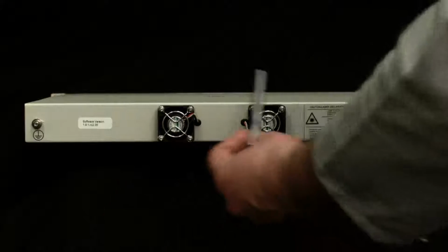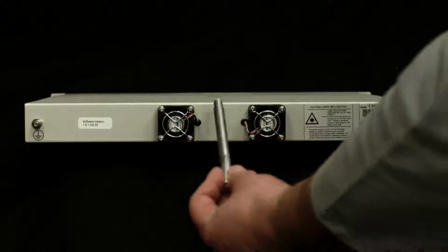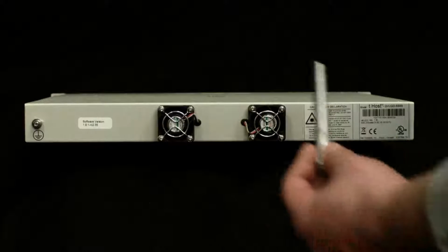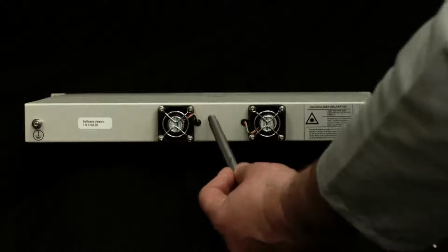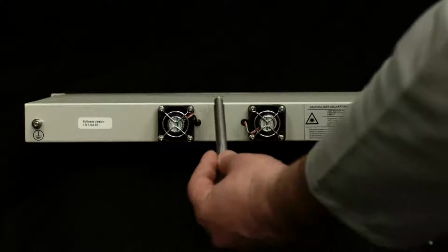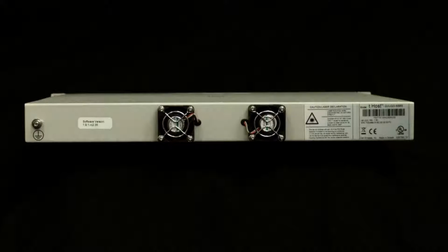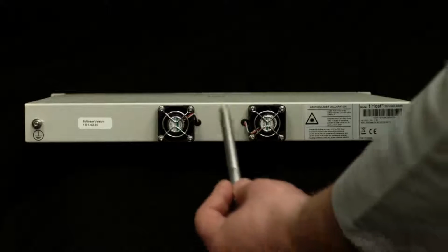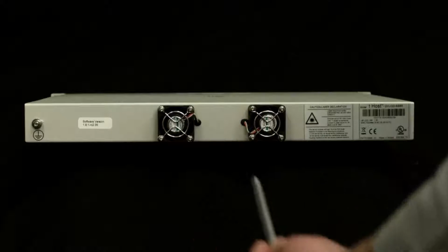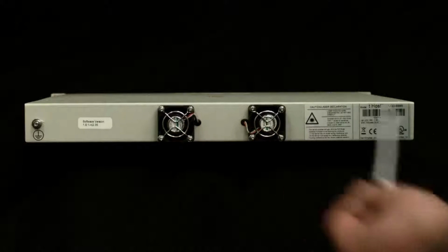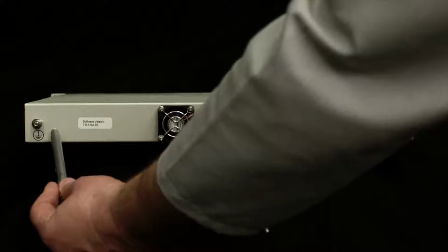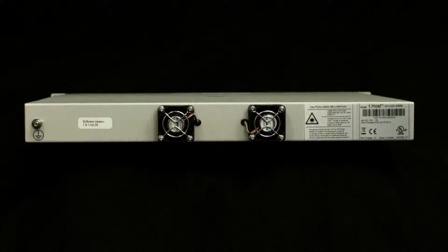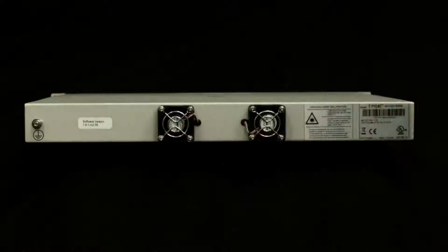The fan assembly is designed in a fashion that it's very easy to replace them. So in a case of the fan failure, by removing 4 screws and unplugging the inline connector, the failed fan can be easily removed. In the same fashion, in opposite order, the new fan can be placed at the same location. Finally, we have a ground terminal at the left-hand side of the unit where the ground lug can be connected and unit properly grounded.